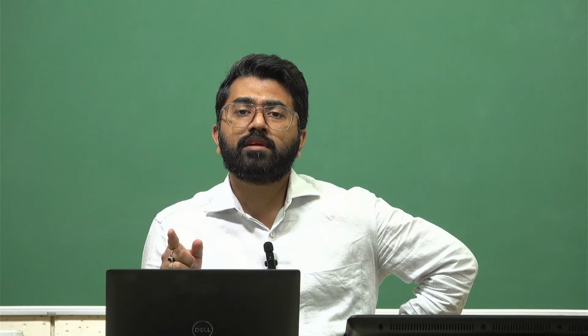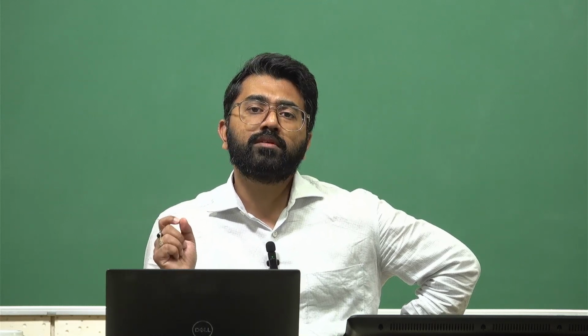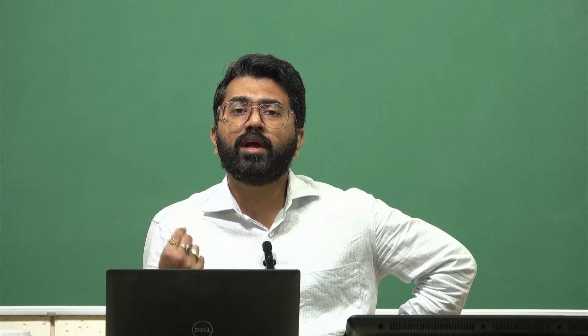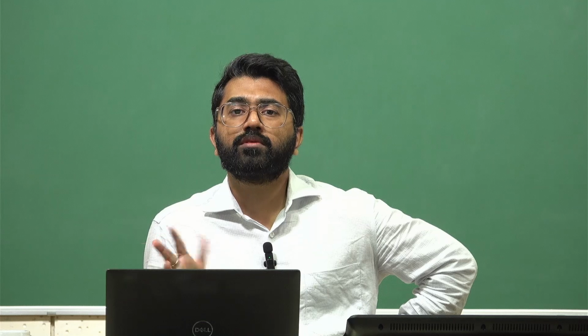Be it through scanning, be it through CAD software, importing from CAD software, or I built it. But the building methodology which I'm using currently is known as a bottoms up approach. This is a point to be noted. So what is a bottoms up approach? Bottoms up approach is when you start from the very bottom of the hierarchy with the points. You go from points to lines to areas to volumes, not the other way around. That is known as a bottoms up approach. Why would I not get the volume directly?